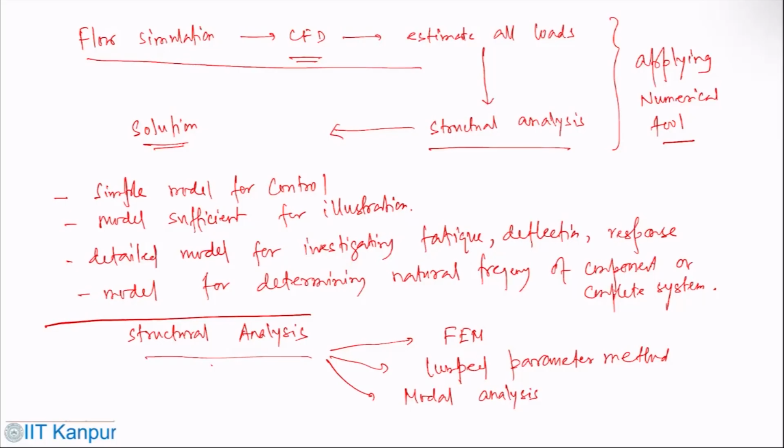So modal analysis again is a method which is used to solve the equation of motion in multiple degrees of freedom vibrating system. This particular approach allows coupled equation of motion to be transformed into an uncoupled modal equation, which can be solved separately. And then finally, the solution from each modal equation can be superimposed to give the complete result. So this is quite useful for linear systems with classical damping.